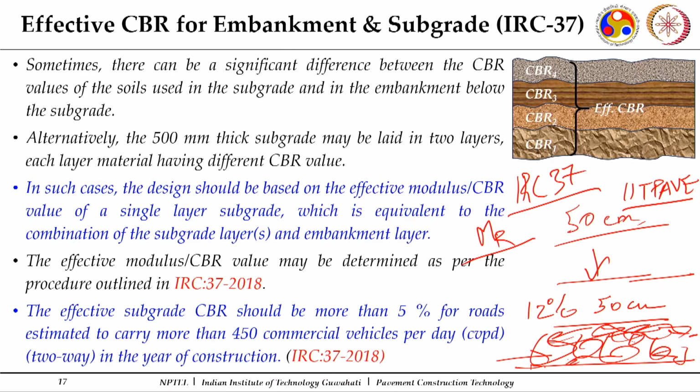So, it says that the design should be based on the effective modulus or CBR value of a single layer subgrade, which is equivalent to the combination of the subgrade layers and the embankment.